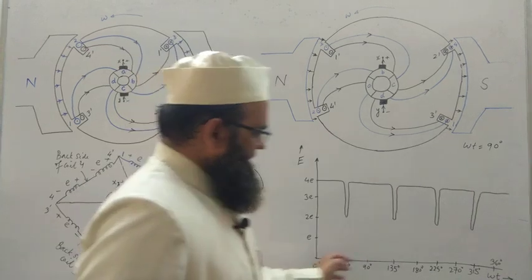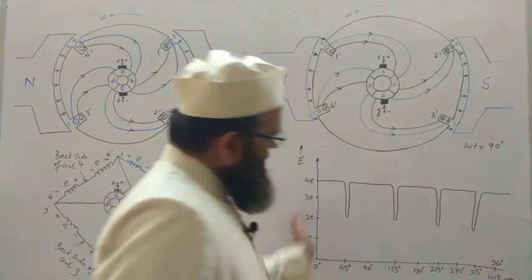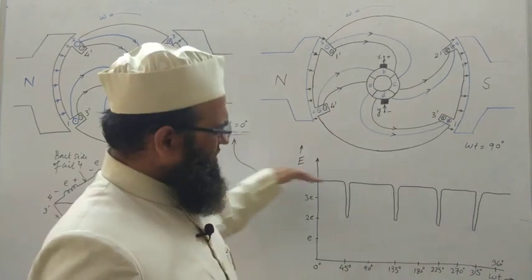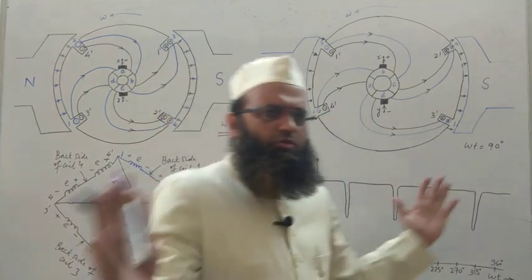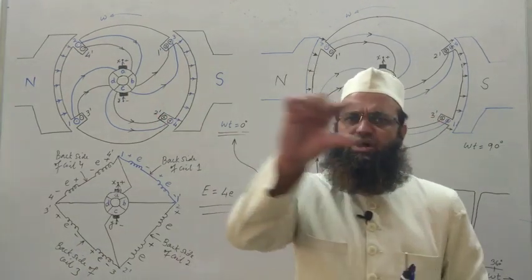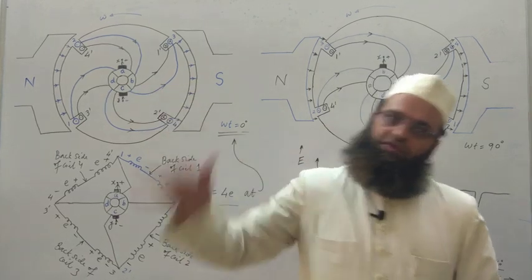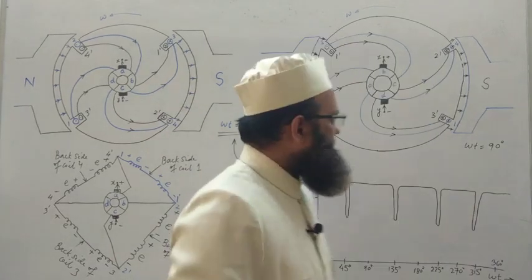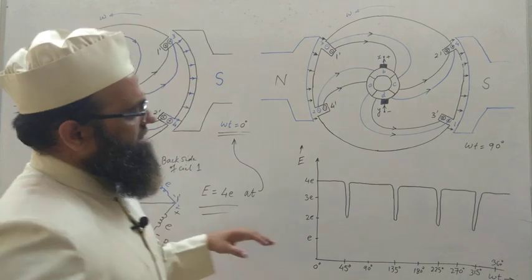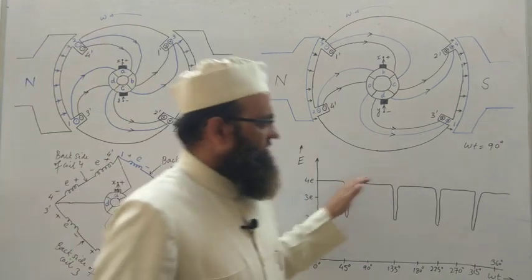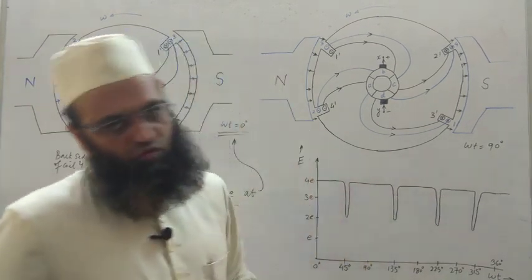In one cycle you may observe waves nearly equal to constant waves. If you observe on a screen, you will see that the output waves are not alternating in nature but have the same polarity, right? So nearly the average value will be constant in nature, and that can further be made smoother by increasing the number of coils.